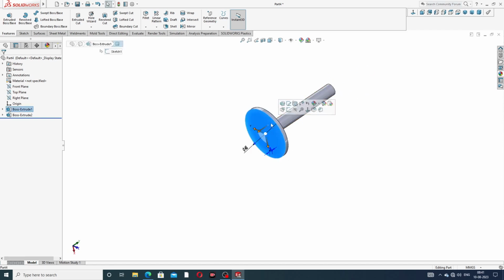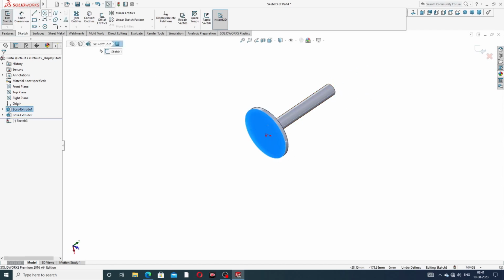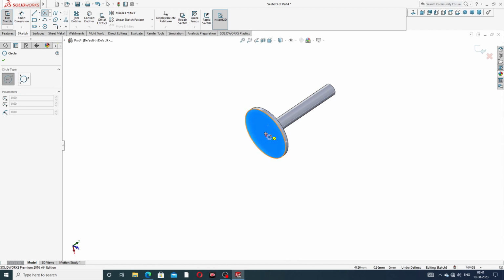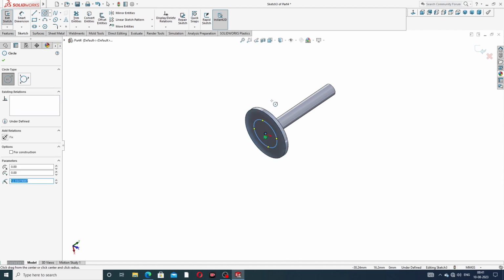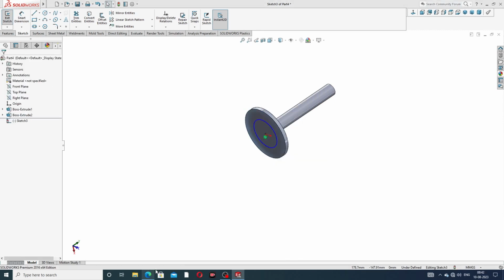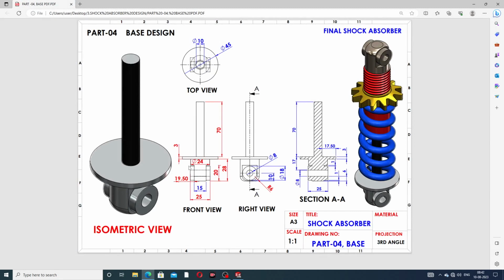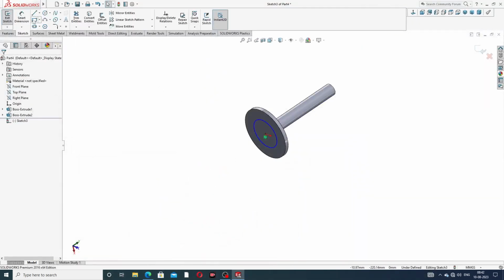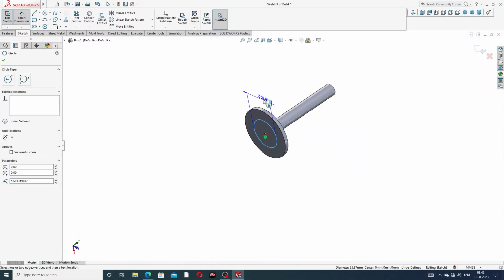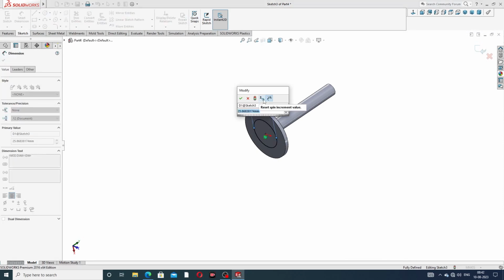And then the back side, also select sketch and draw a circle, and then on the back side, this diameter is 24 millimeter and this length is 28 millimeter. Okay, and then a fillet is applied here, a 6 millimeter fillet, and align this diameter, this is 24 millimeter,